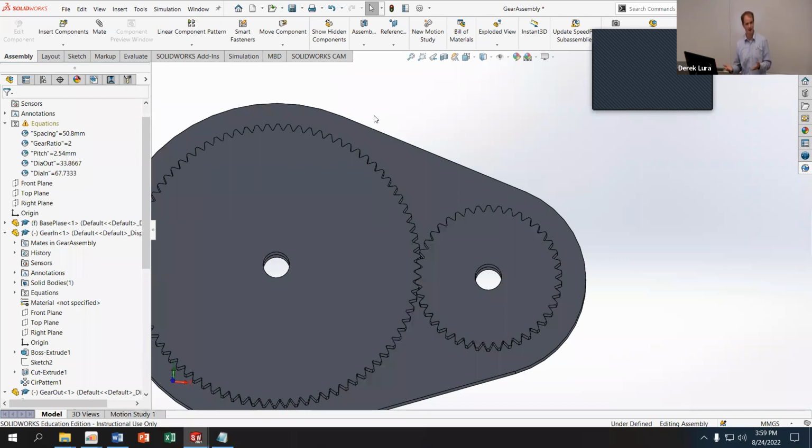But if it's fast, high power, like a motor, like an engine for a car, it's turning at thousands of RPMs with potentially several hundred foot-pounds of torque, right? At the same time, that's going to be a problem. And if you're designing a power plant where you're doing megawatts of power, you're going to tear a gear like this apart in fractions of a millisecond. It's just going to get destroyed right away. So we need better gears than this.